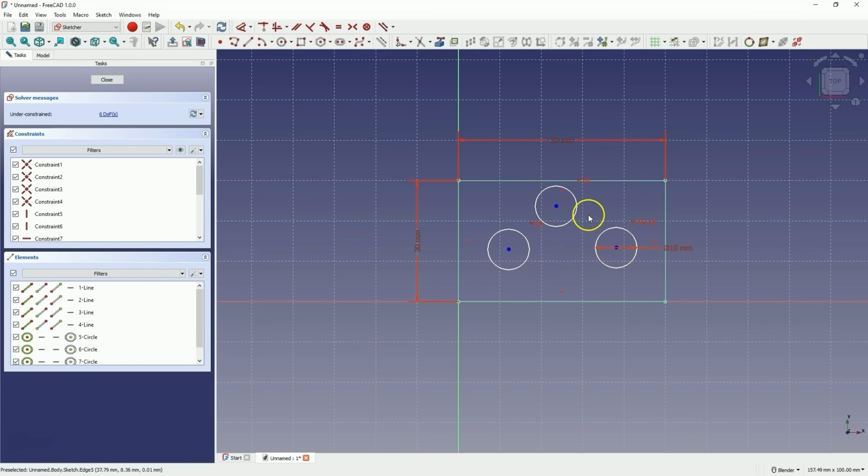In such a situation, where we have many identical geometries in a sketch, and these geometries have the same dimensions, it is a good solution to use constraints instead of specifying the dimensions of each geometry separately. As in this case, we linked this geometry with an equality constraint. Now, if I need to change the dimension of those circles, I simply change the dimension of one circle, and the dimensions of the other circles change automatically. This can save a lot of time when creating 2D sketches.